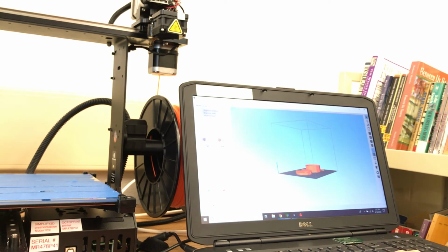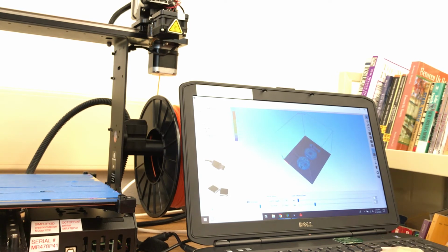Step 1, insert your STL model. Step 2, define your process. Step 3 then is to prepare to print. As I prepare to print, I could go look and watch these layers play, as they are going to develop. Once my layers are set, up here in this corner it'll tell me how long this is going to take. It's going to take about 4 hours and 19 minutes.